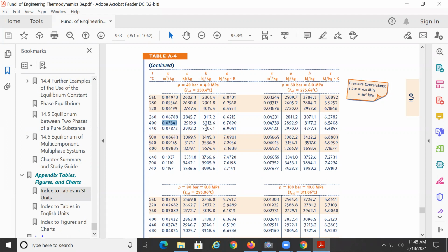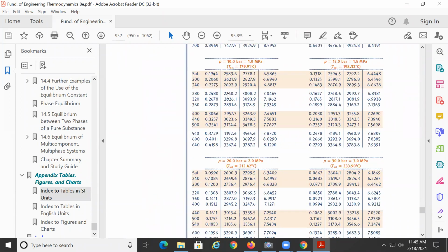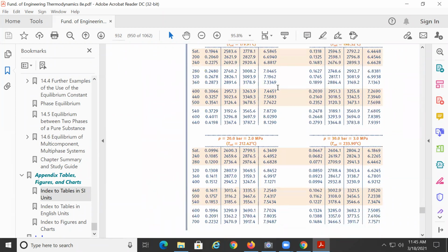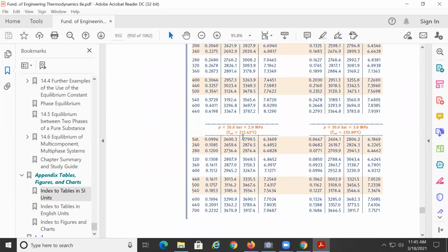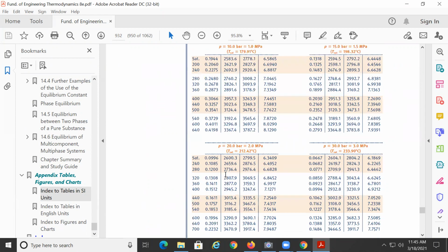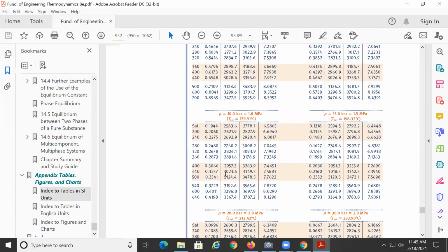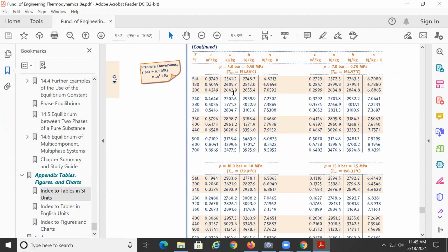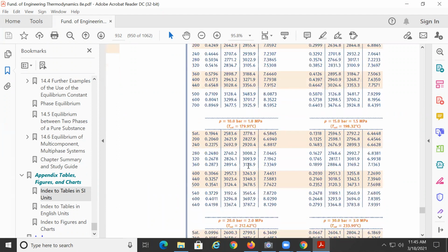And at P2 equal 20 and T2 equal 400. So I guess this is still, maybe we'll find it out of this table. Is this correct? 20 is here. What is the saturation? 212, no? So it's still vapor. And at 400, the H, I think, is the third column. Yeah, it's this one.